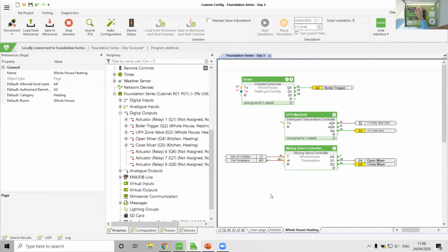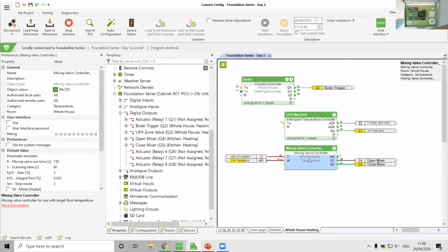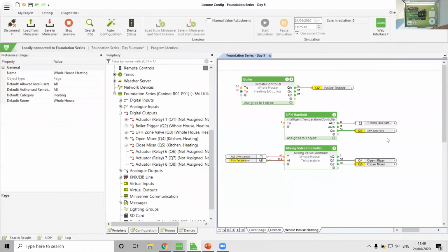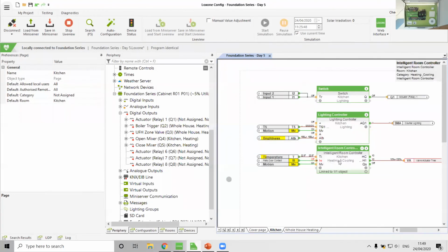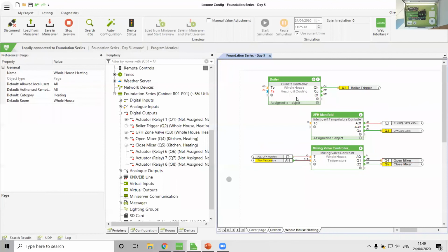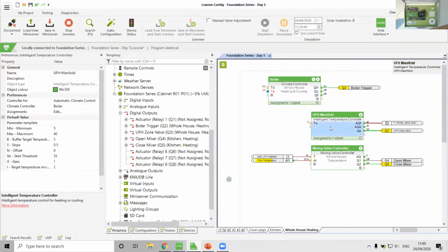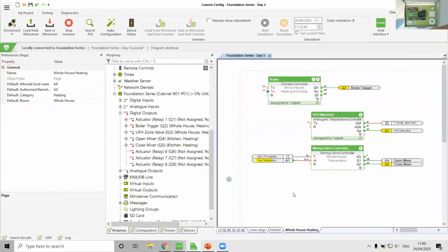So as I start twisting this potentiometer, you can see there that the temperature is adjusting. If I go above or just roundabout our desired temperature, so we're now at 51.9 degrees flow temperature and we want to be at 40. This has a 60-second sample time. So after 60 seconds, this will start adjusting itself as required. But there we have it. We have the room level, the boiler level, the zone valve level, and the mixing valve level.